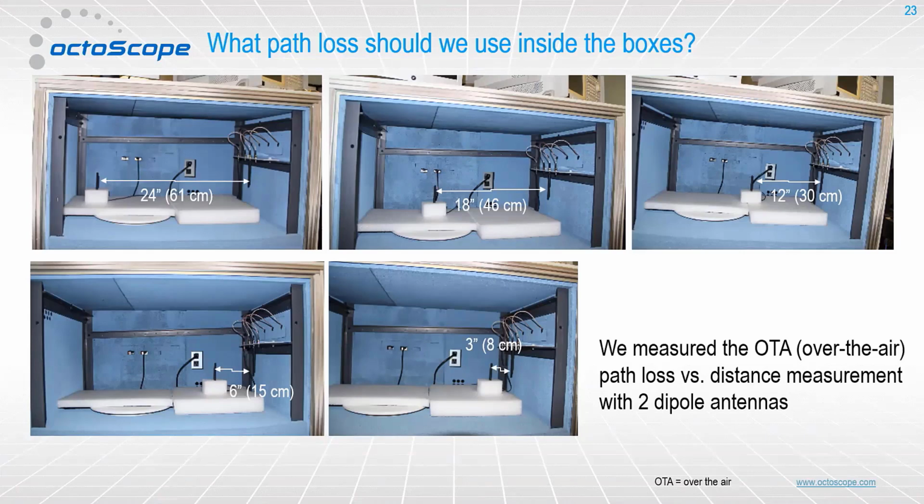So essentially, between any set of antennas, we're getting a free space model. In order to support MIMO, we would have, let's say, 4 antennas here, 4 antennas here, and between any pair of antennas, we're seeing free space propagation.